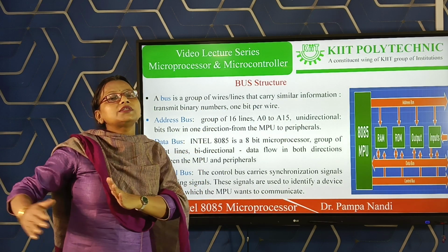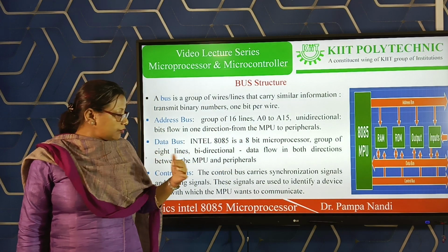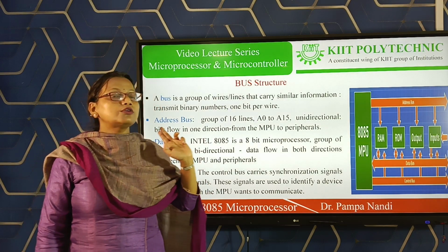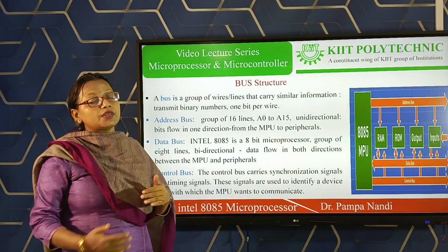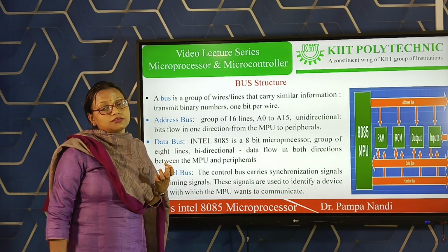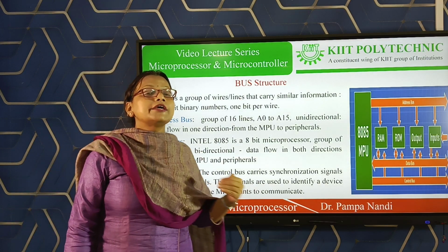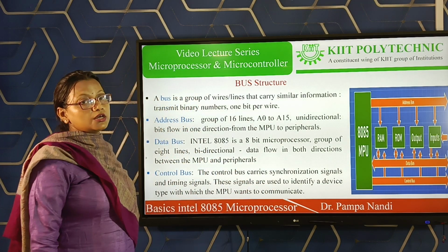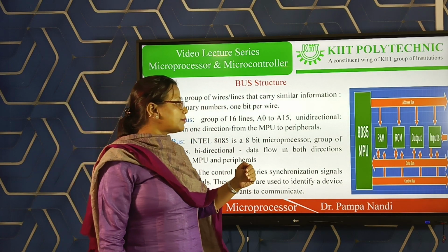So, your bus is carrying information from the input. At that time, the printer is not connected, maybe your input line is getting data from the keyboard. In that way, which device the microprocessor wants to communicate with, and at which time, should be processed through some control signal. So, the microprocessor also generates the control signal, and the lines through which the control signal passes are called the control bus. So, there are three kinds of buses you can see: address bus, data bus and control bus.